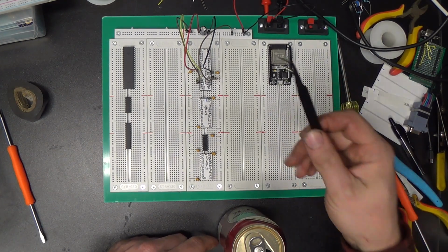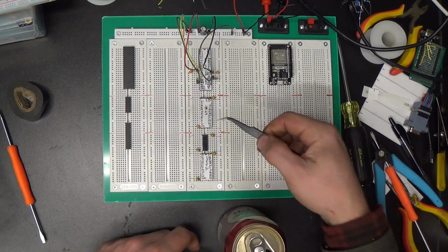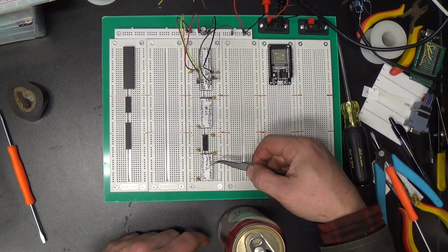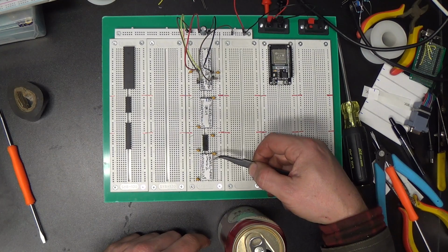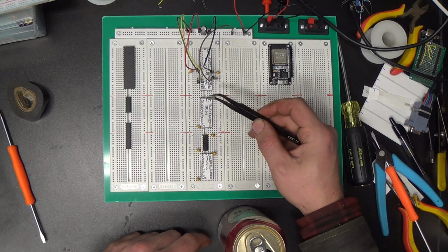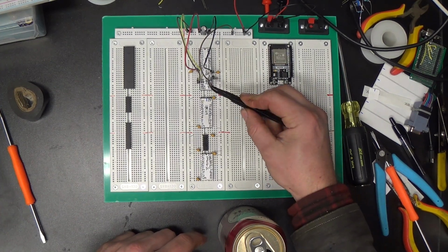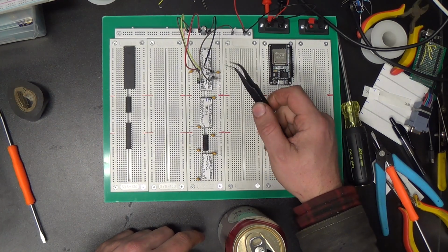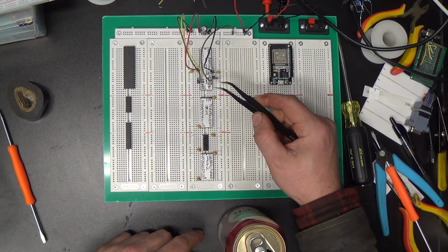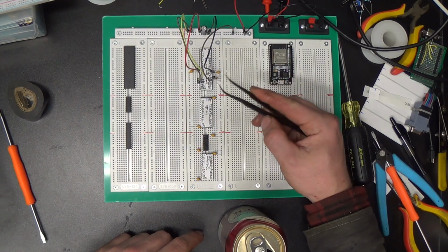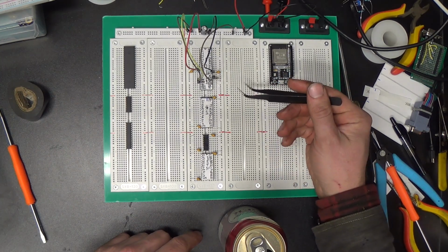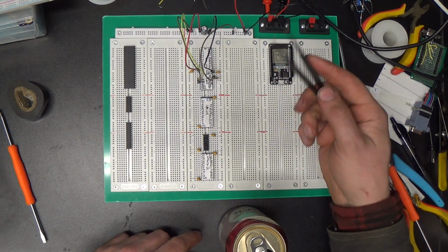Alright, so, as we mentioned yesterday, we have a ROM, a 28C64, and a RAM, a static RAM, a UM6116. And we need to interface both of these to the Z80 processor. Now, when we reset the Z80 processor, as you recall from previous Z80 Funtime videos, it begins executing at address 0. That is the reset vector, 0. It fetches an instruction from address 0 and evaluates that instruction. And it just keeps doing that.